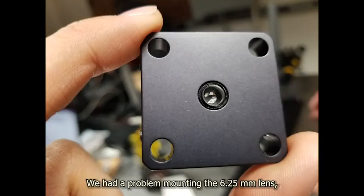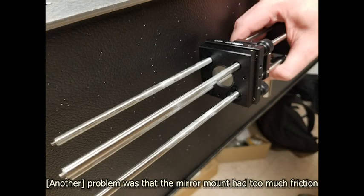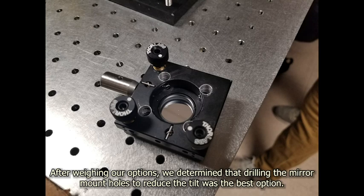We had a problem mounting the 6.25mm lens as the lens was too small. The problem was that the mirror mount had too much friction with the rail, causing the actuator to tilt the mirror, disturbing the optical alignment even after adding lubrication. After weighing our options, we determined that drilling the mirror mount holes to reduce the tilt was the best option.